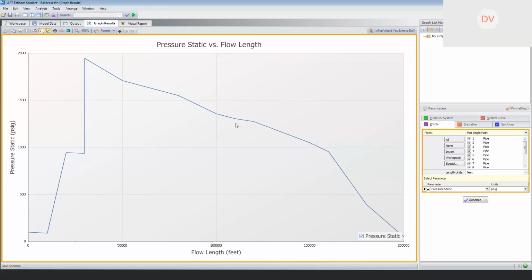So at your lowest point, just downstream of the pump, that's your highest pressure. As you go up elevation, the pressure drops, and it finally arrives at the solution that you need this much pump pressure to be able to achieve the 50 psi based on locating that pump at that particular location.